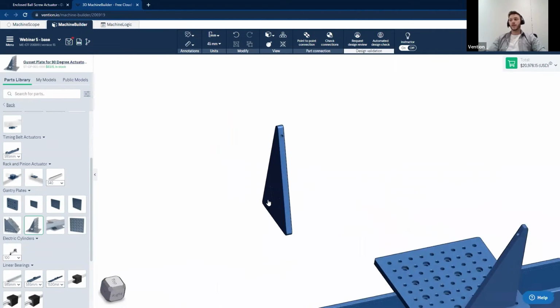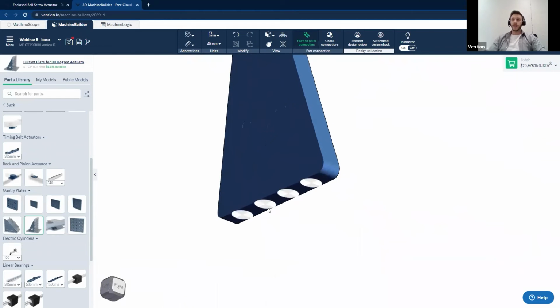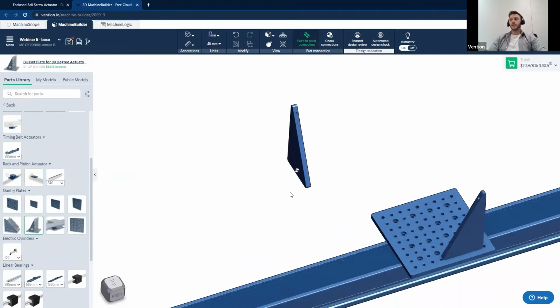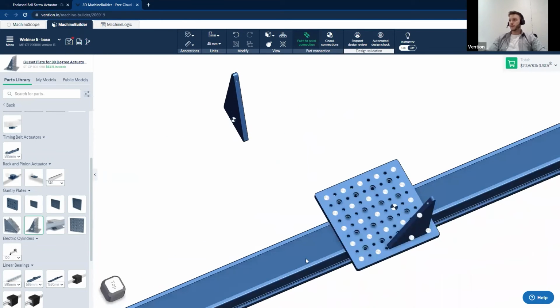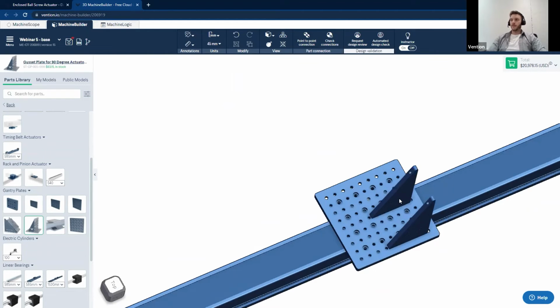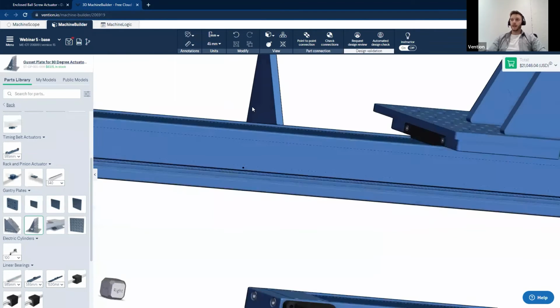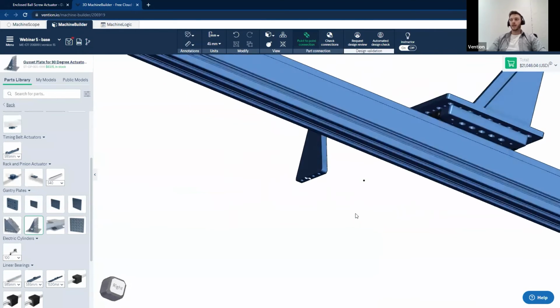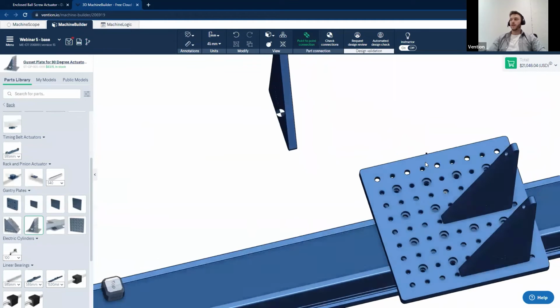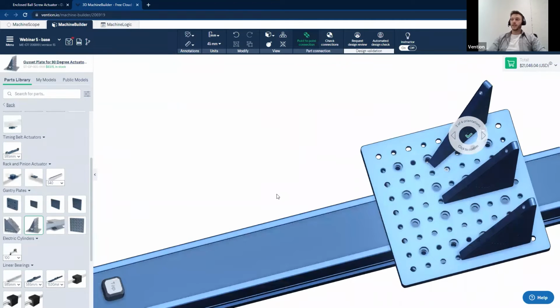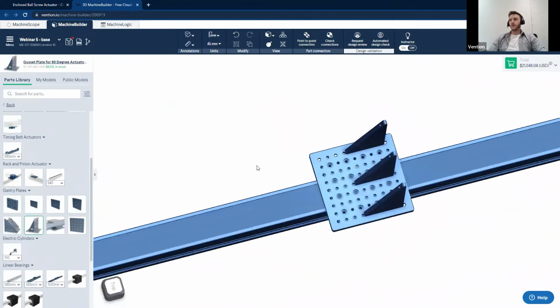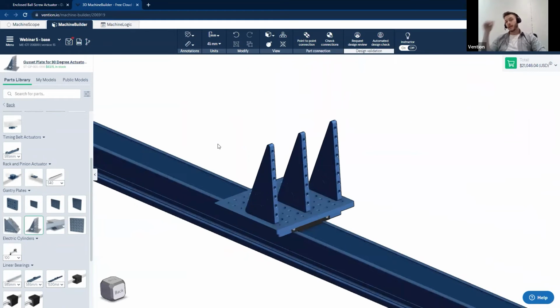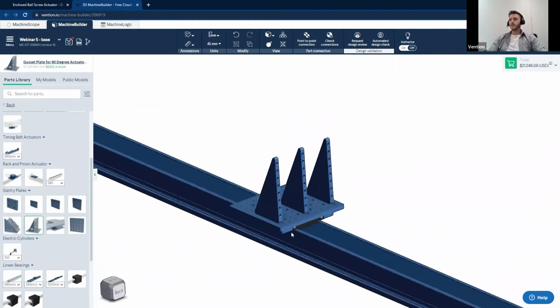If you are interested in learning how, there is a tutorial on designing gantry robots that follows some very similar steps to what I'm showcasing right now. So for this one, we're going to have 3 of these mounted over here. And another shortcut that I'm using, you'll notice that I click on a part and then the part will appear at the end of my cursor. This is me pressing the I or the insert key, which allows me to reinsert the last inserted part in my design.